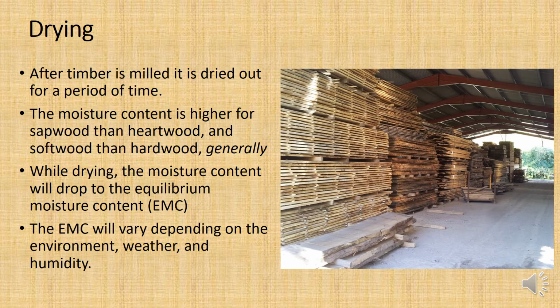So just so you see here, that picture on the right, that's a drying shed. My best friend growing up, he actually lived on a farm, and they had a forest on the farm, and so from time to time they would cut down trees and mill the timber from the trees, and they would stack the wood in this drying shed. And you can see in there that where the timber is laid, there's little spaces in between all of the timbers. Do you see that? That's so air can get in between all the different slots and dry out the timber individually.